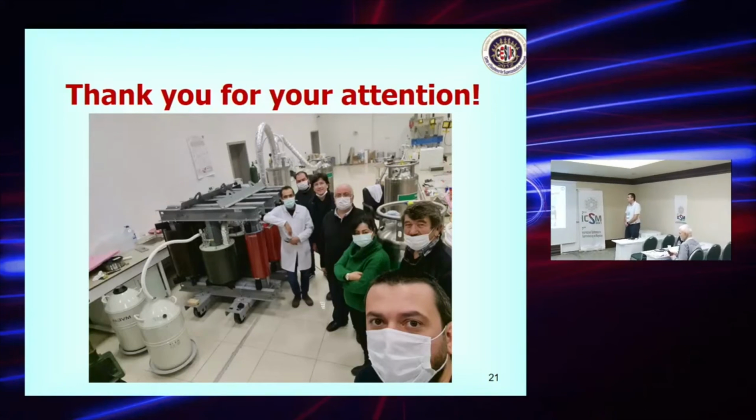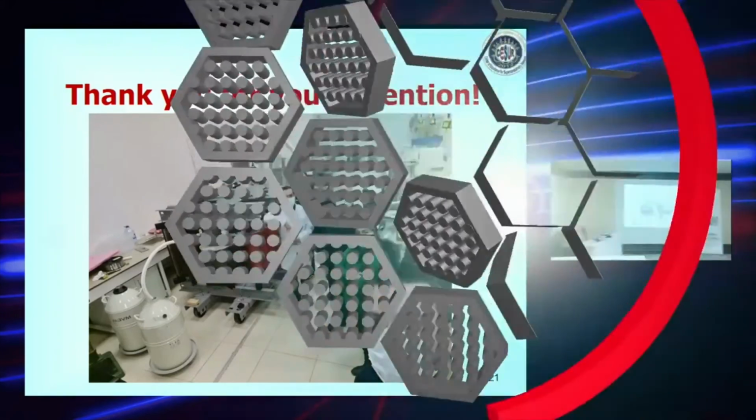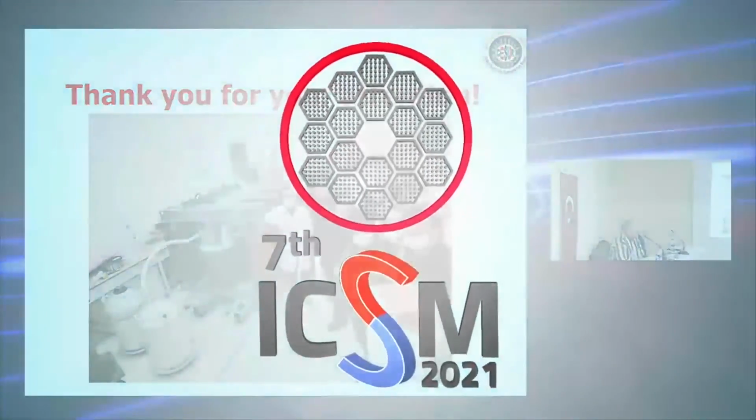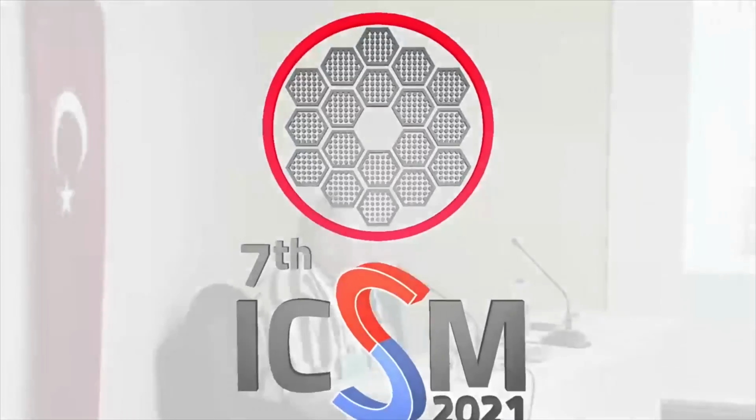I have a very naive question. Transformer steel is saturated at 2 Tesla. Does it mean that you use just low currents? Again, please. The transformer steel saturates at 2 Tesla. After that, the transformer does not work. Yeah, we are also using saturation, but a bit different from the saturated core FCLs. Because for a saturated core, DC current is additionally applied, but we don't use it.